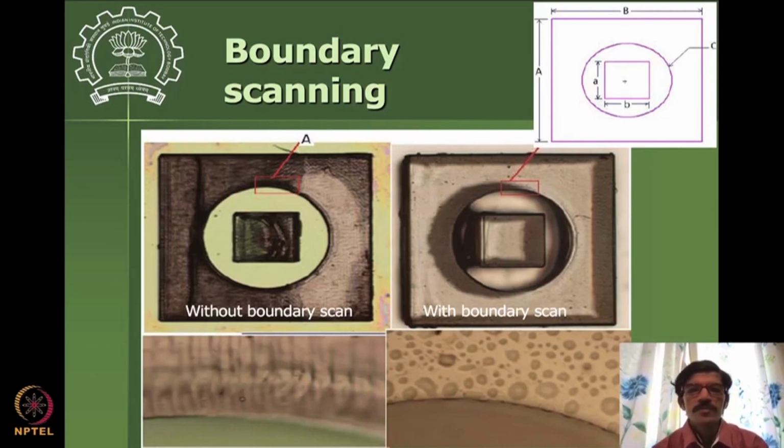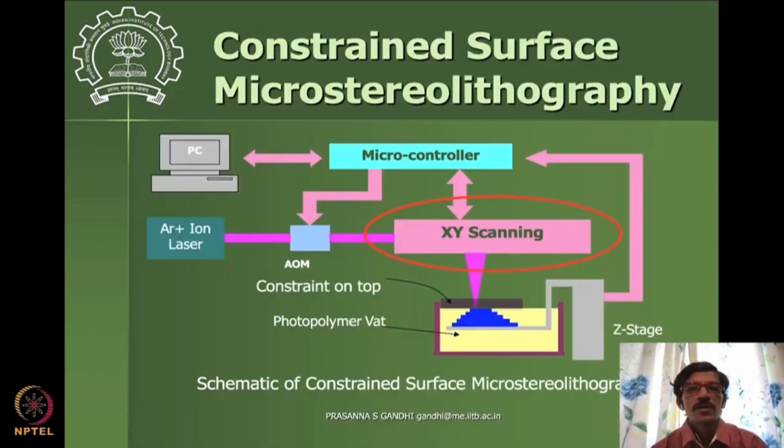The basic mechatronic system remains the same, like you have these XY flexure based scanning stages, and there are some interesting control algorithms that are needed for this kind of scanning, because you don't want to get into vibrations of these compliant mechanisms. Okay, if they start vibrating in an unwanted way, then you'll start seeing inaccuracies in your positioning.